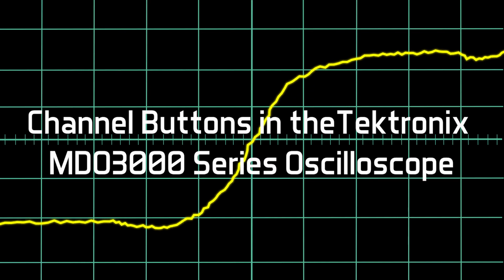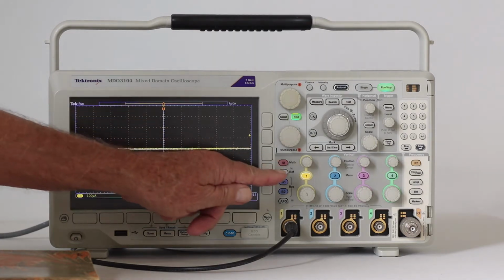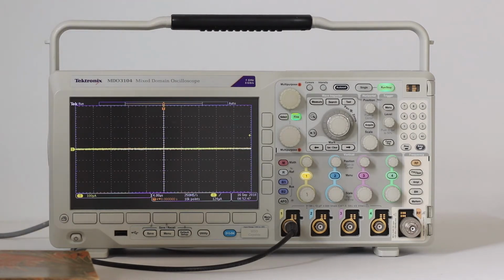Today we'll look at what seems to be a simple and modest oscilloscope control, but actually it accesses quite a multiplicity of functions that are basic to all oscilloscopes. It is the channel button, one for each channel. In the Tektronix MDO3104, there are 4 channels and 4 buttons, each in its dedicated channel color.